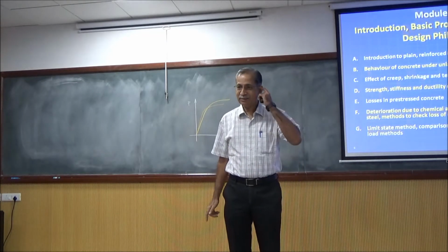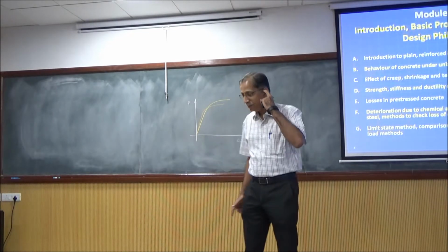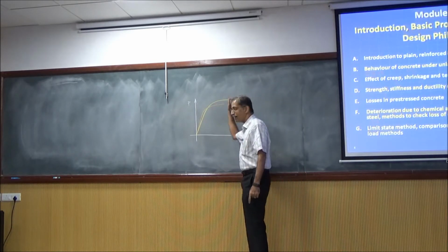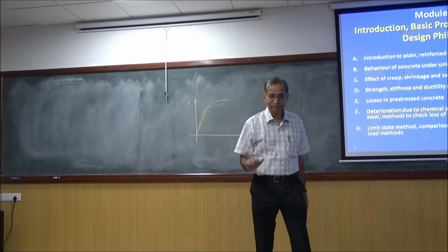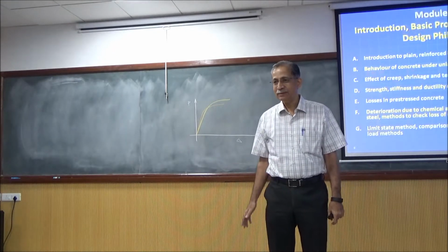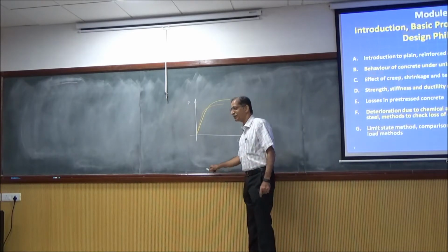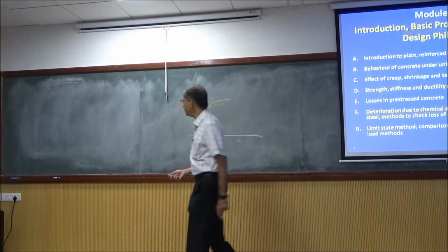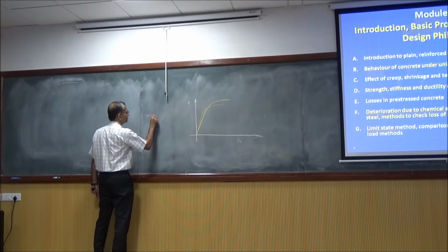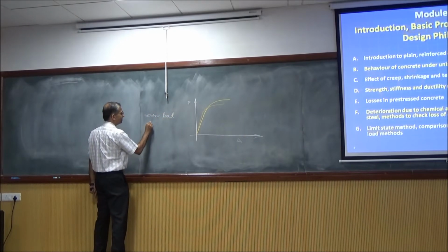Whereas stiffness relates to load per unit deflection. Now, can you talk about stiffness for either of these two lines? You have to be careful. The word stiffness applies only to the initial portion, then later on it collapses. So we have typically service, we have ultimate.